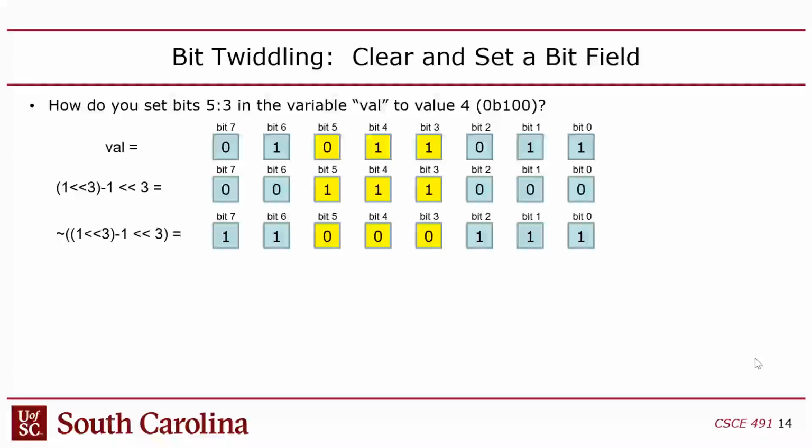I mean, you can do your operation on the control register and then print the control register, but then it's in hex. As a human, you just see a hex value, and you don't know the temperature. This temperature field doesn't even fall on the hexadecimal boundary because it's 5 down to 3. These numbers aren't divisible by 4, so this doesn't even correspond to a hex digit inside of a hexadecimal value. Very difficult to debug this, right?